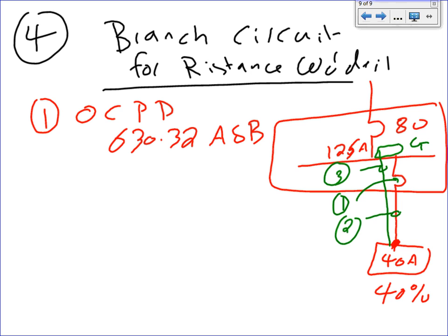You're right, except they could be different types of circuit breakers and fuses with different characteristics. I'm going to leave this one for the short circuit guys. You can have a 200 amp fuse here and a 200 amp circuit breaker here, and the fuse will not trip but the circuit breaker will trip, or vice versa, because of the characteristics of the fuse, the way they design them, the trip curve, and so forth. So it would make sense when you look at the current characteristic curve of the fuse or the circuit breaker they're using either here or here.